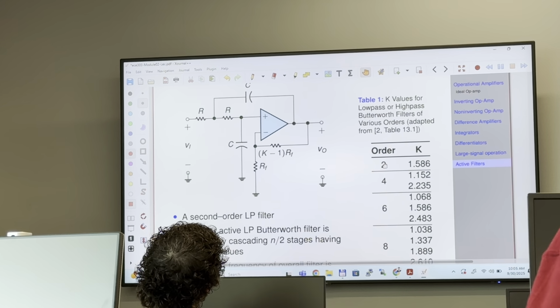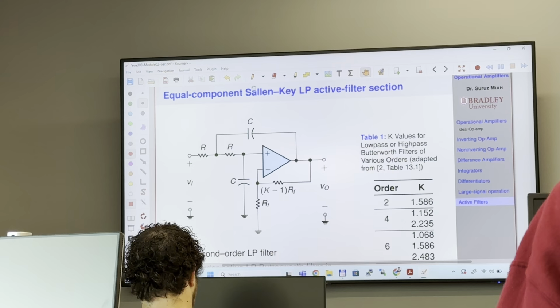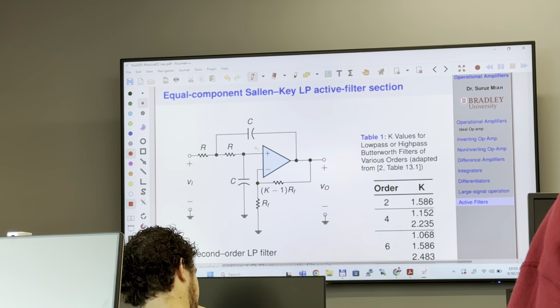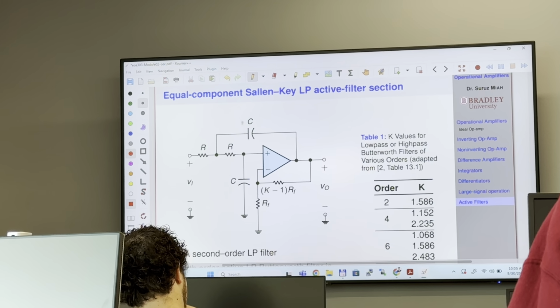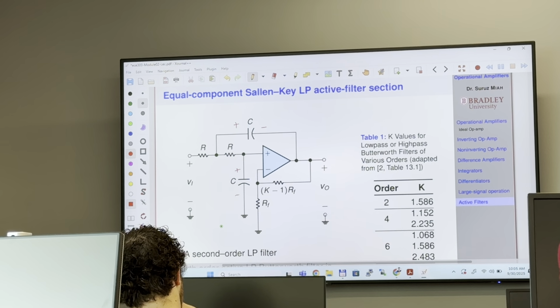What does the bent line on the capacitor mean? Because there's usually two straight lines. Okay, this bent line means it's a polarized capacitor, it has a polarity. Positive here, negative. These are polarized capacitors. Very good.